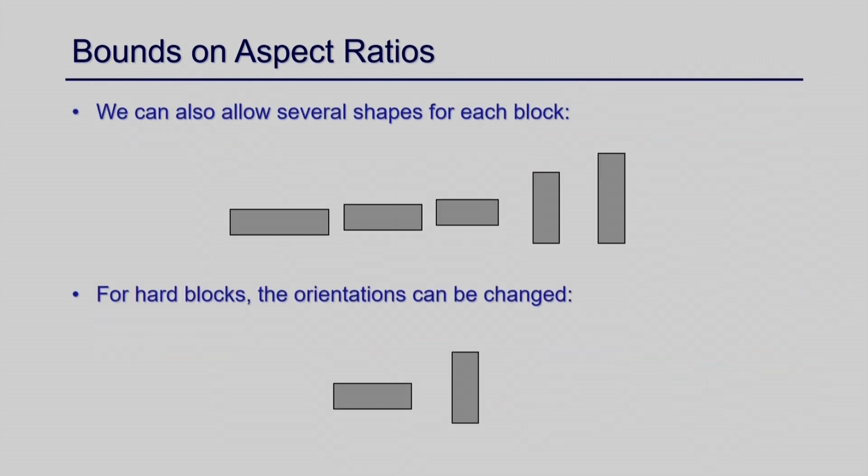Okay. So, as I mentioned, for the same size you can generate different kinds of blocks, and also the orientation may be this way or that way. So, you have to consider all possible such orientations given the aspect ratio constraint, and then you try to place all those blocks in the area, so that your primary objective, to reduce the area, is met and you can place all of them in the smallest possible area, right. This is floor planning.